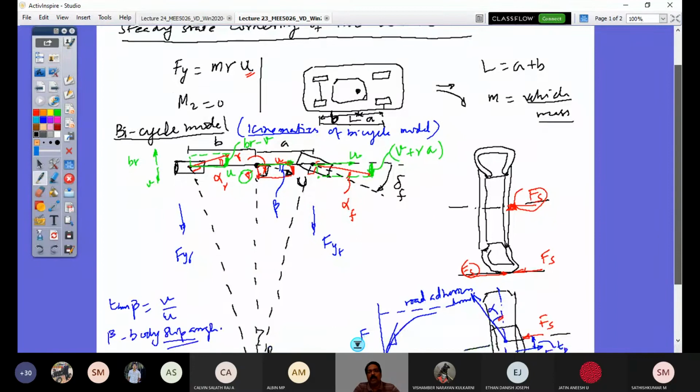So what's happening when you give a steering is only an orientation change with a constant angular velocity, the yaw rate. It is not changing with some angular yaw acceleration. Then that state is not called steady state, that's called cornering state, right? That we will see in today's lecture as well. So what would happen if I have Mz equal to Izz R dot, right?